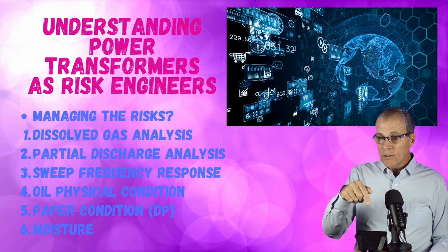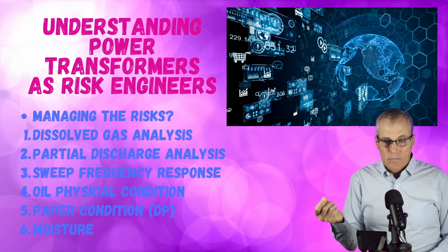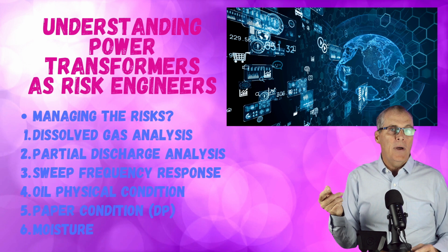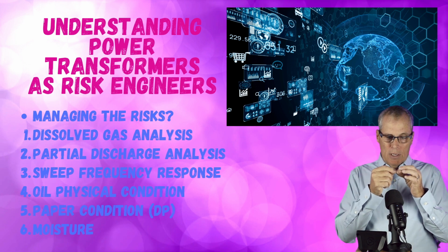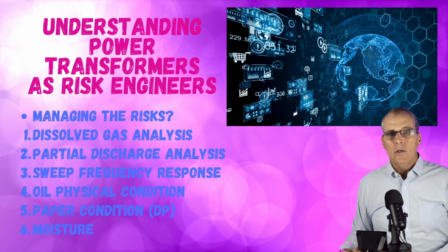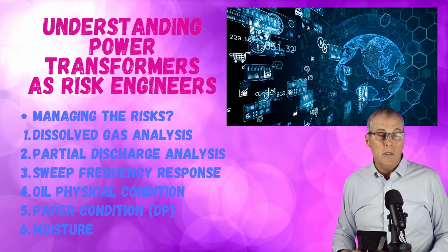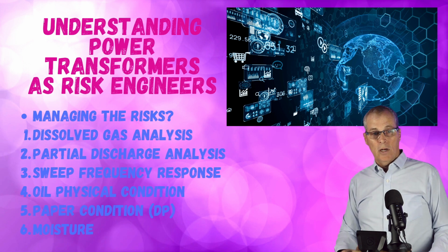Remember, we have oil insulation and we have paper insulation. You can tell how old the paper is or how weak the paper is basically by getting a piece of it and pulling it, right? So there's special tests where you can go in there and take a clipping of the paper and determine really how much life is left in the transformer.